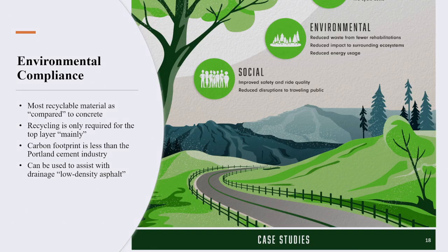Environmental compliance. Everyone knows what RAP now is, right? RAP, recycled asphalt pavement. In the US right now, there are two major terms that we have in the business of asphalt: RAP and RAS. RAP is the recycled asphalt pavement that we know, and RAS is the recycled asphalt shingles. In the US, especially in residential construction, wooden construction is used big time. So they have asphalt shingles on top of the roof, right?